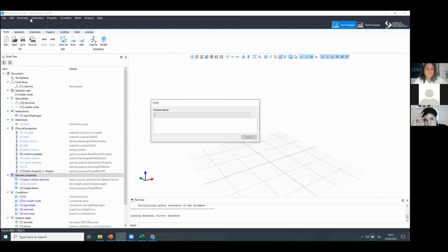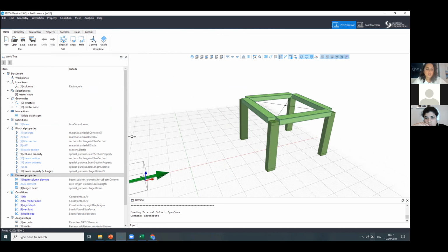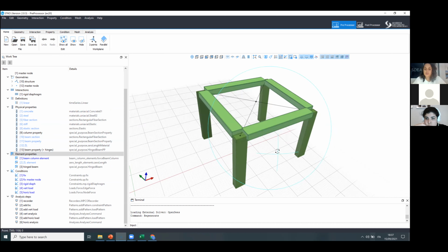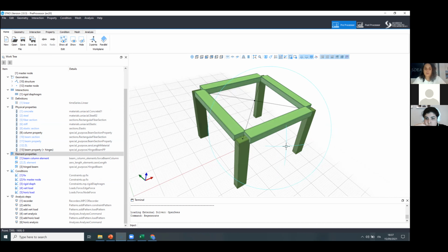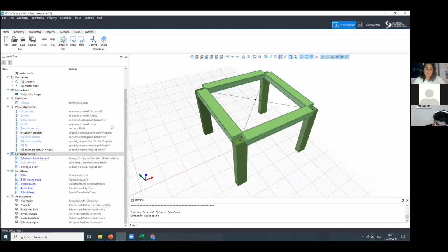So for each of these files, there is one of the three approaches. It starts with the distributed, and this, for example, is the finite length approach. And you will see the application of the same materials there. What you can do as an exercise, if you want to understand how this works, is if you have a large frame structure, you can take the sections and make some small models like the ones that I showed you before to extract the moment-curvature response of that type of section. And so calibrate your phenomenological law in the spring in order to be able to apply a lumped plasticity approach.